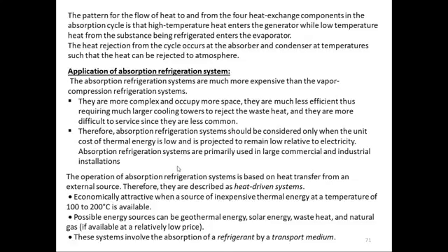a good viable option. You need to have cheap thermal energy available for a long period of time, at least 10-15 years, because the cost of the vapor absorption plant is large. So unless you have low cost heat available for 10 or 15 years, installing this will not be a viable idea. You have to have low cost heat available for 15 years or maybe more. Then this idea will be viable. There is ongoing research on how to make it cheaper and smaller, but currently the situation is what I'm trying to mention here.